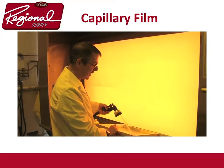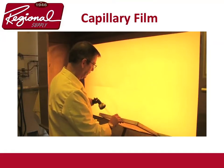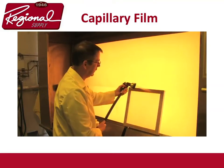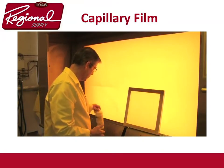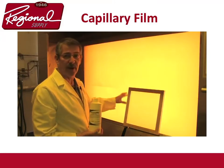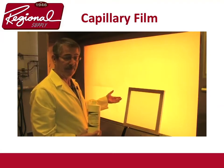You have to do both sides. Make sure you get it all off. Okay, it's now degreased. The next step is you have to put on a wetting agent. What this wetting agent does, it actually makes the screen wetter. It keeps water on the screen longer, giving you enough time to apply the capillary film.